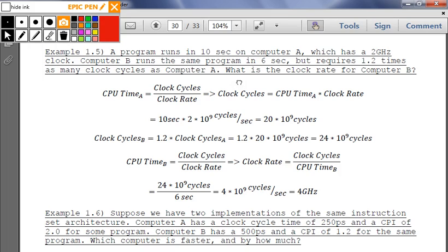Yes? As far as today's technology, what becomes the limiting factor in these? You mean in the advanced digital section, what are the limiting factors for frequency? Okay, so interconnects, power. Interconnects meaning you have these buses that go between, and I think somebody was asking a little bit about level 1, level 2 cache. So the idea is you have to transmit information. A significant amount of power is consumed between these interconnects, as much as, I read one paper about a month ago that said up to 47%. So that's one limiting factor, these interconnects.